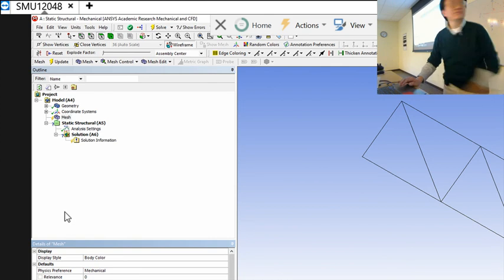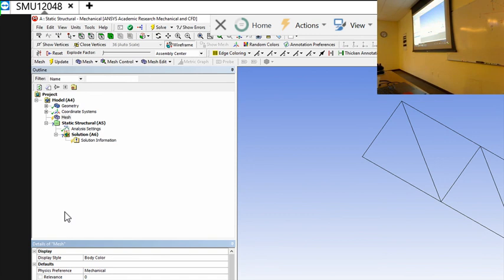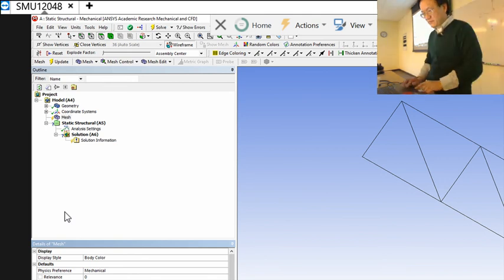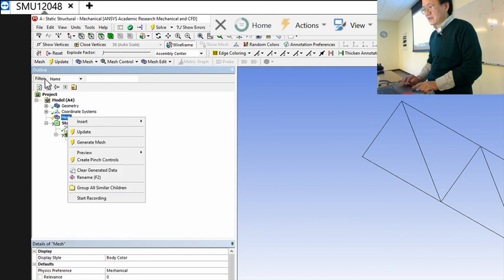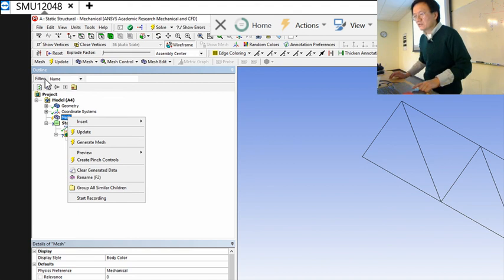You will see element size. Slow down a little bit in case you miss this. And change that size to 100. Default, you click default, and type in 100, in millimeters, very small. Then the Enter key. That's what you do. You can change various sizes, but for this structure, 100 will be more suitable. Now next, you go to the mesh icon again.